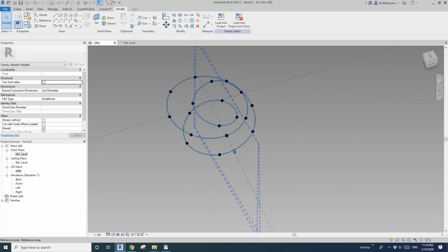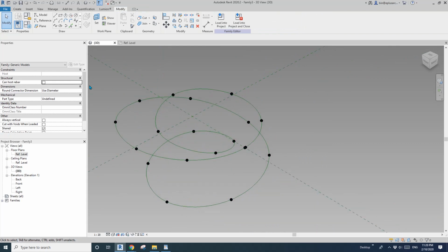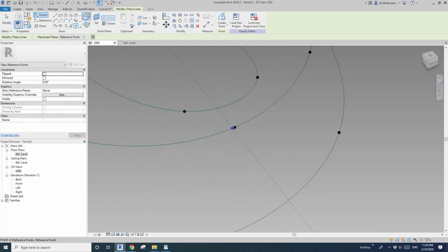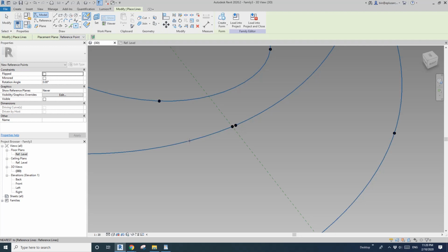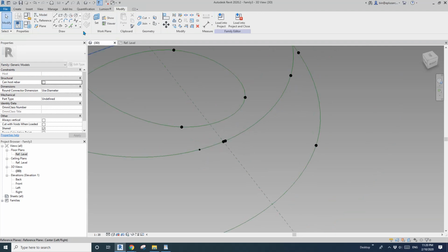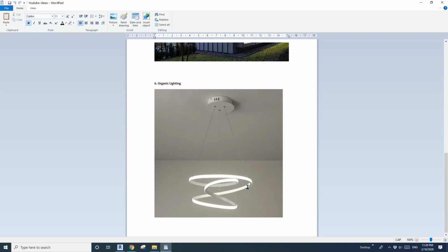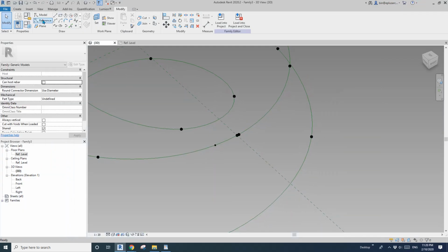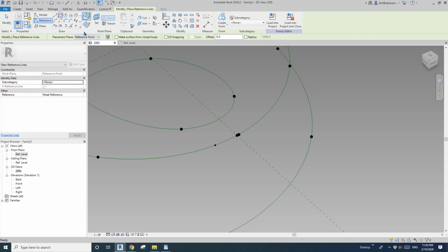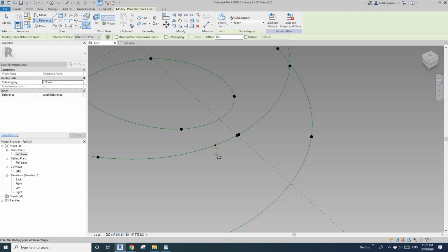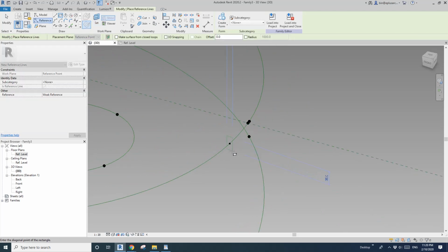Now I'll just place a point, draw our face, and I'm going to place it close to the first one. I'll place it here, and then draw a profile. In this exercise, it's going to be a rectangular shape. I'll draw a reference rectangle, draw our work plane, set work plane, pick this work plane, and draw a rectangular shape.